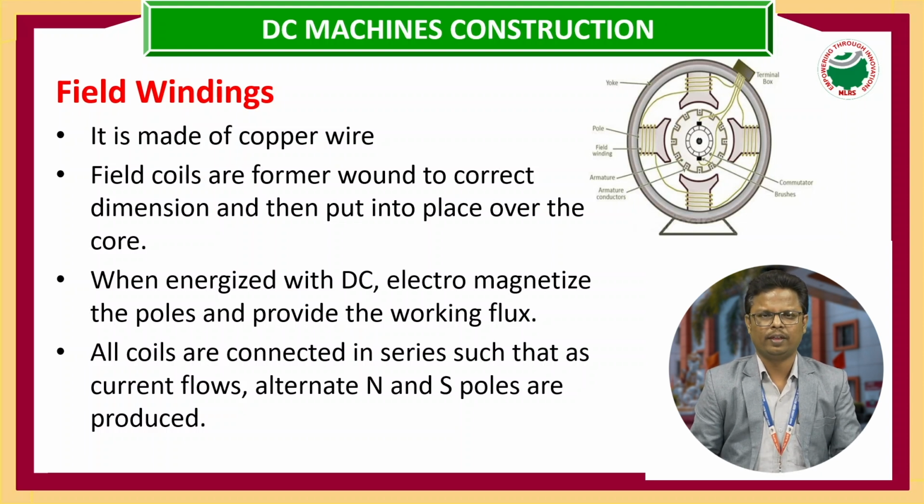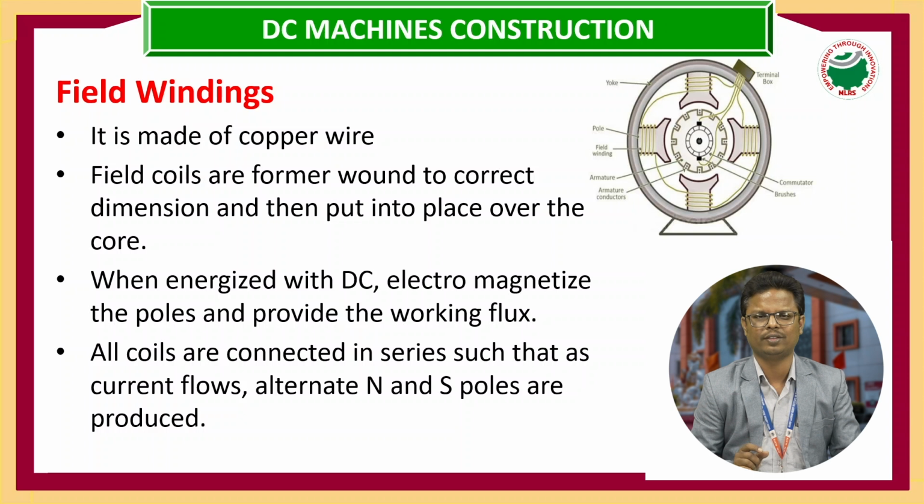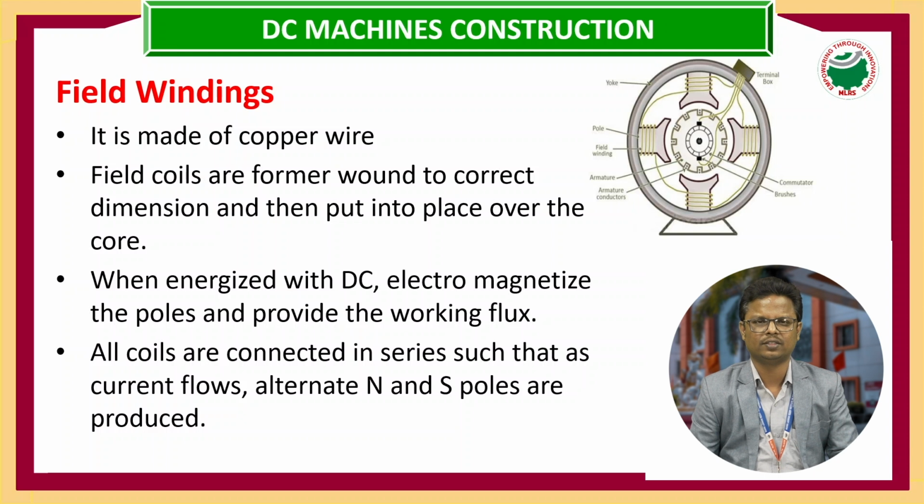If the flux lines leave from north to south, then we can easily conclude that the leaving point is north and the entering point is south. So by using the thumb rule, we can conclude which pole is north and which pole is south. If two consecutive windings carry the same direction of current, there is no formation of a pole. If the current directions are different, there is a formation of a pole. To know which pole it is, north or south, we use the thumb rule.